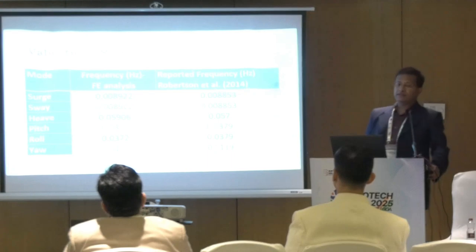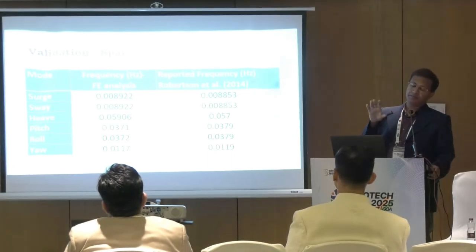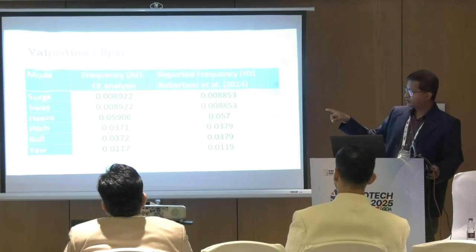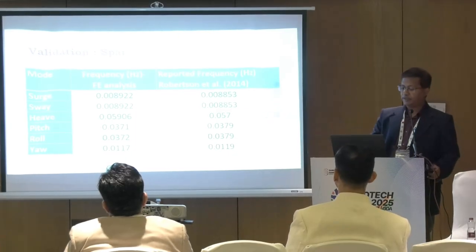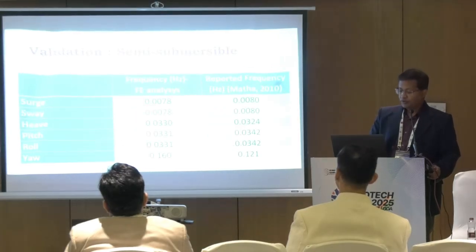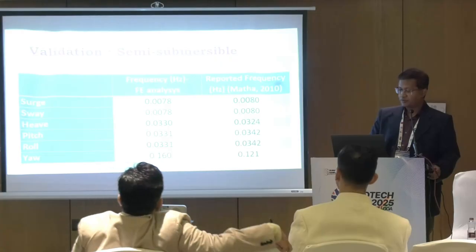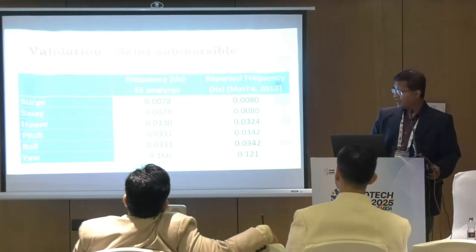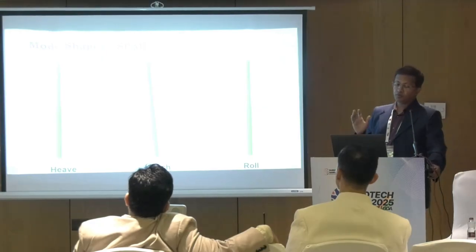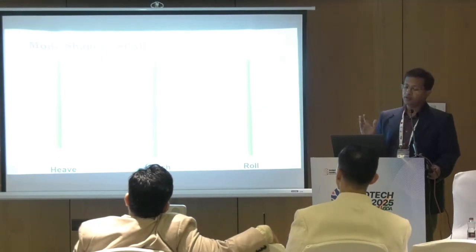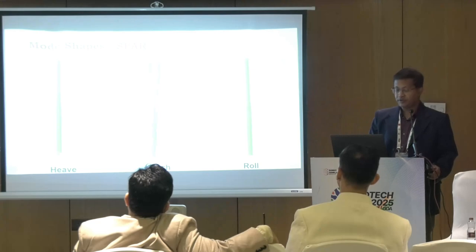Now, if you look at the validation, we tried to validate using the natural frequencies of different modes of vibration. These are the frequencies based on our analysis and the reported frequencies in the literature, which match quite well for two different types of systems, the semi-submersible as well as the spar. TLPs I have not presented here. And if you look at the animation for different modes of vibration, these are the heave modes, and the pitch and rolling frequencies based on the modeling concept that we have adopted here.